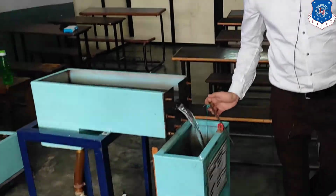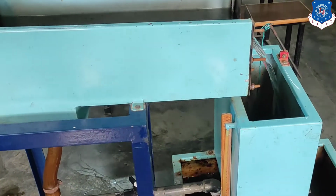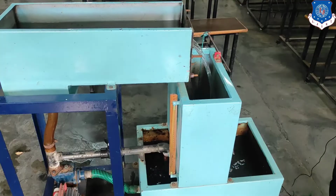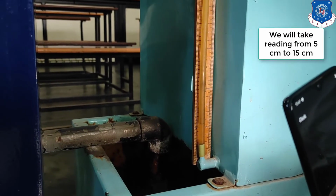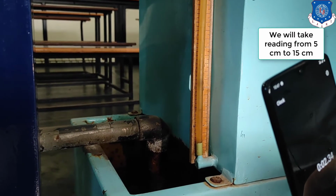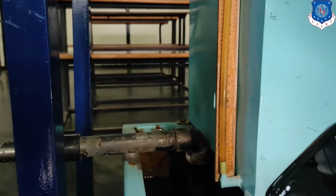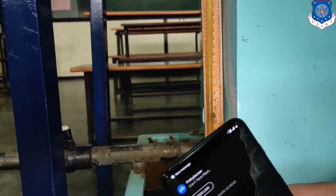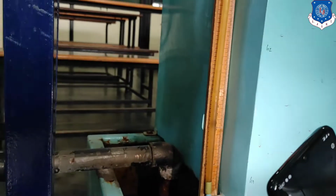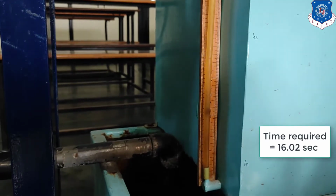So let's find the actual discharge first of all. For finding out the actual discharge, we have to close this lever operated discharge valve. So let us close this lever operated valve. We can take the reading from 5 to 15 centimeter. Okay, we will stop our stopwatch at 15 centimeter. Okay, so our time required will be 16.02 seconds, right?